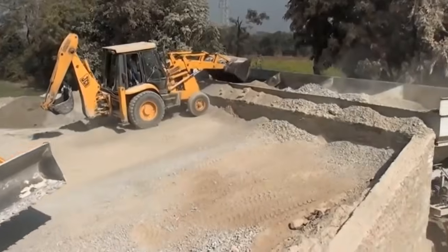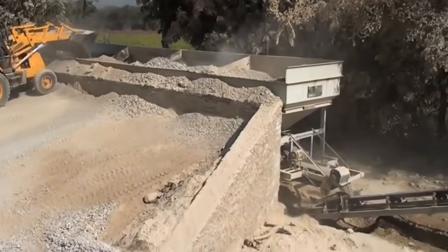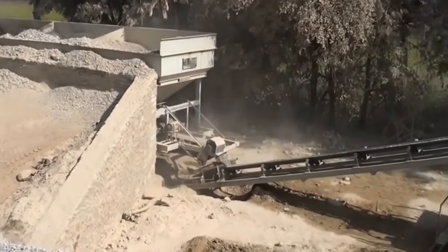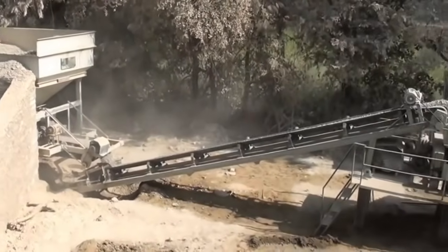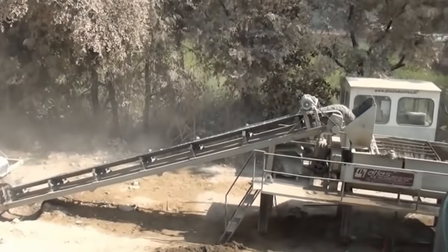Now, the next item of work is Wetmix Macadam. Wetmix Macadam is the next generation of water-bound macadam, and it is intended to be an alternative and more durable pavement in roads and highway work. It is generally used as a base course of flexible pavement. WMM provides uniform and strong support, and high resistance to deformation and distress.